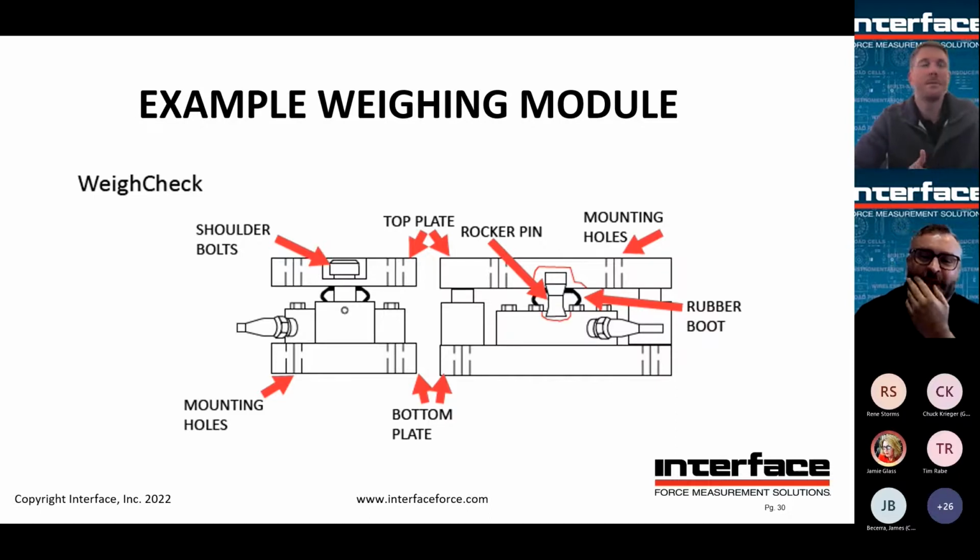And maybe I'd like to expand on this a little bit too. Why weigh modules instead of just bolting a load cell straight into the system? Ideally, if you bolted everything together, it might work. But as the temperature changes, the tank expands and contracts. Or if you fill a tank, the legs bend a little bit. So there's all kinds of extraneous loading going on.